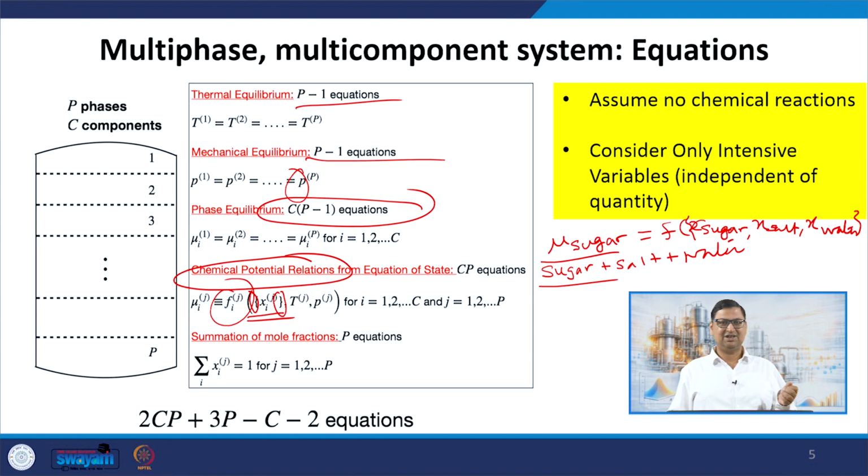So, equation of state, although I am writing it in this particular way, may appear to be simple, and I am not going into details about different kinds of equation of state or my recommendations for this, but this is the area where things can really go wrong. So, take that equation with great seriousness and choose the proper equation of state if at all you are doing any process simulation.